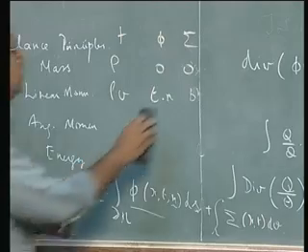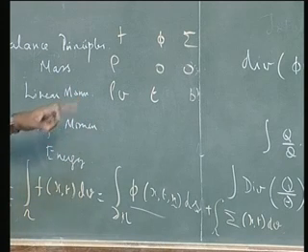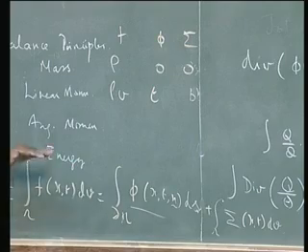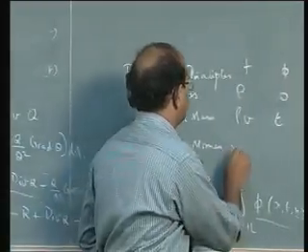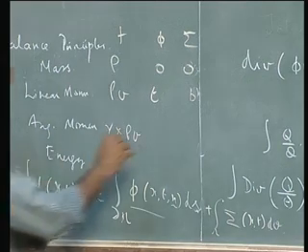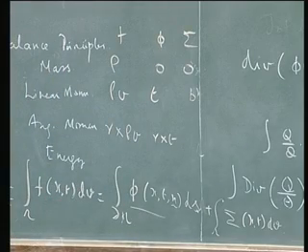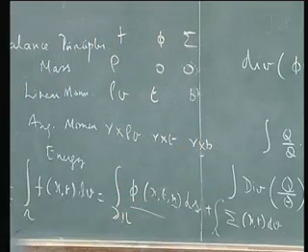Since n is common, you can say that phi is nothing but the traction t. So rho v, t and b are the three terms which will go into the conservation equation. And lastly we have the angular momentum equation: r cross rho v, r cross t, because we are taking momentum about, say, the origin, and r cross b are what will go into these three terms.